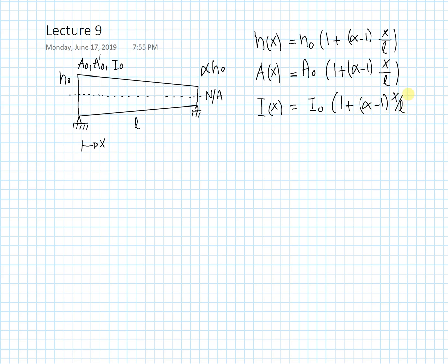For this particular example, I choose to ignore shear. So what I'm going to do is let A naught prime equal 0. And by doing that, I'm going to fully ignore the contribution of shear towards deformation in this structure. And I also have the area equaling 100 inches squared, the elastic modulus equaling 29,000 psi, and the moment of inertia equaling 900 inches to the power of 4.